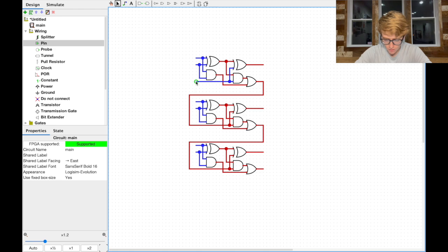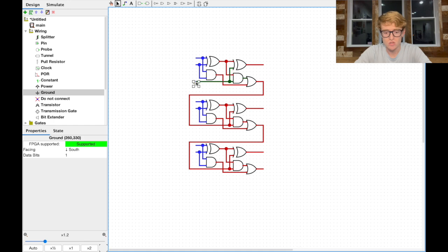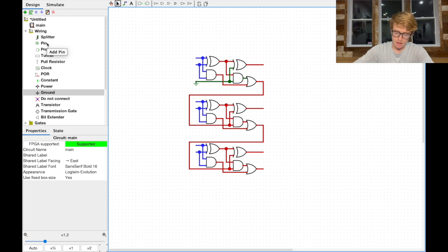Okay? So now, the carry in on the first full adder, you might be wondering what's going to happen with that. Well, there is no carry in for that one, so we're just going to put a ground there. So that'll be a logic 0. The carry in is just always 0 for that one because there's nothing that comes before. Okay, so now we need some way to establish a constant 1, because every time we're incrementing our counter by 1. We could increment it by some other value. We're keeping it simple here, and we're just going to increment it by 1. So how do we create a 1? Well, I'm going to choose to put my 1 on input B.